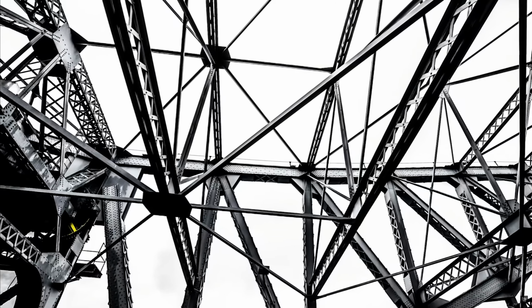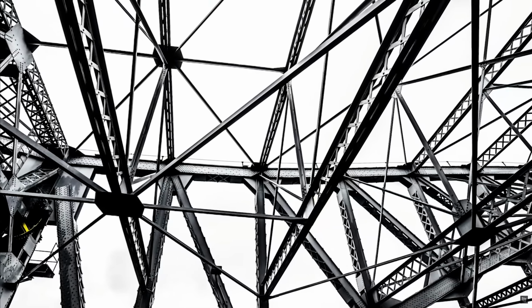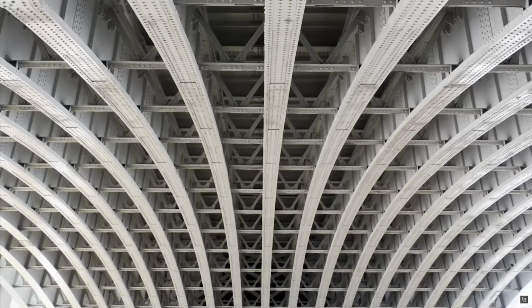Steel, unlike concrete, is extremely strong in tension. It can resist forces that attempt to stretch it. And so while we are making beams that perhaps are going to experience a lot of bending, we want something that can resist the compression at the top and the tension at the bottom, or vice versa, depending on how it's expected to bend. So how do you make a material that resists heavy loads?